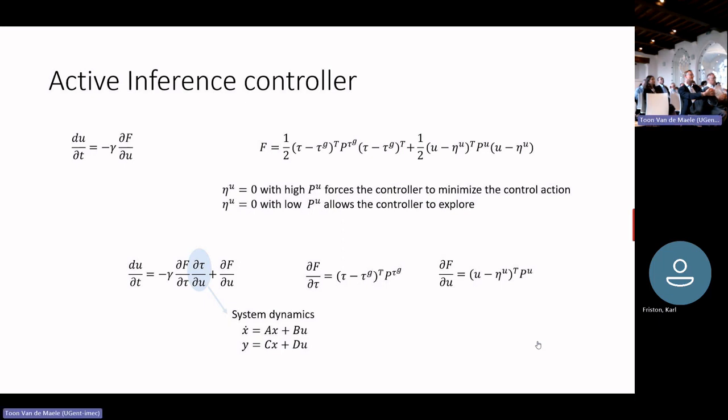It need not be, actually. Imagine that you have a system here and you're now going to control not position, but velocity. Then your task variable becomes dou x dot by dou u. It can be any task you want to do. The only condition is that you should have an expression that relates this u with your x somehow.